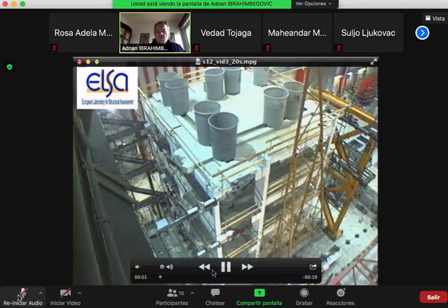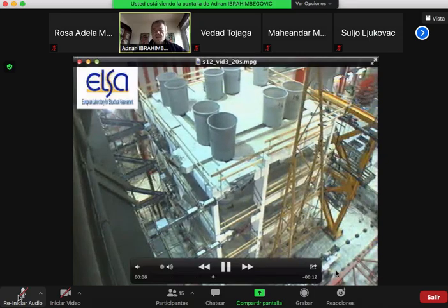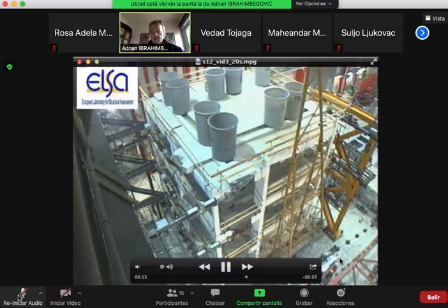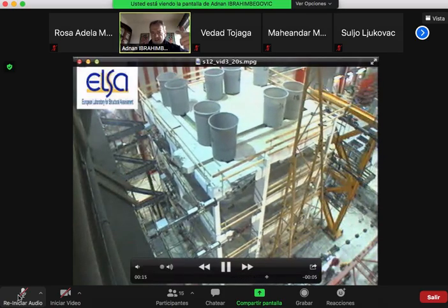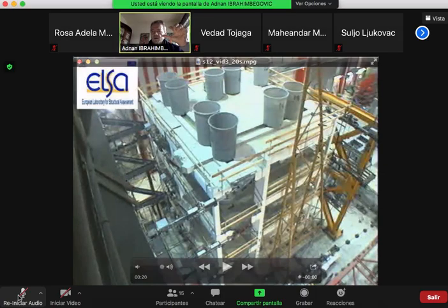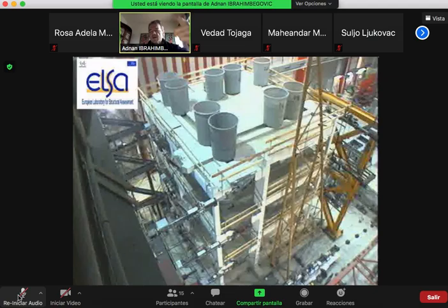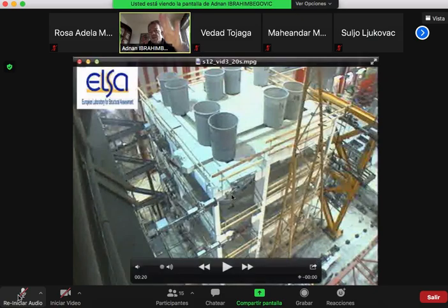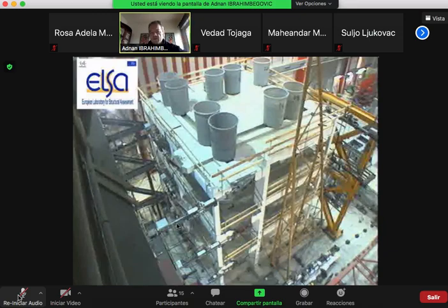Here I show you this movie. You can see that you keep pushing this against the reaction wall, so the structure starts shaking like a real earthquake, and you can see these little ants going very quickly. In reality, this movie has been sped up, so it looks like an earthquake. Otherwise, in reality, the way they do these tests, they predict the acceleration of the earthquake, then they go to the equation and compute what would be the corresponding displacement. Then they move the structure with this displacement at the level of the floors, and then they get the reaction from these hydraulic jacks.